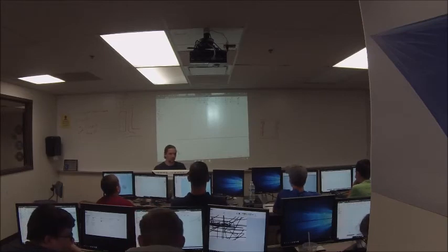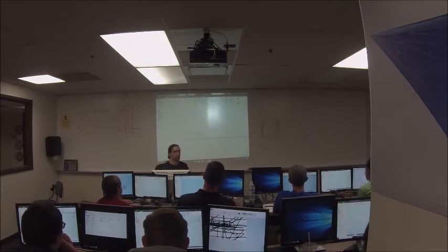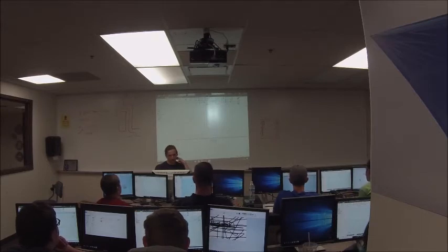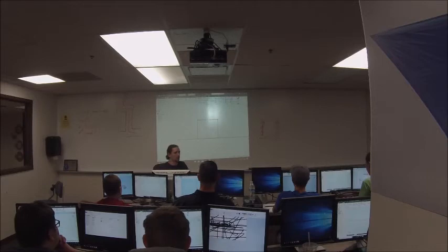Okay, now a rectangle, for instance, there's nothing special about a rectangle. A rectangle is just four lines that automatically have coincident constraints attached to them, right? That's all a rectangle is. So I can make a rectangle here, and then let's say I want to do something weird on this corner, and I don't want these two lines to be attached to each other anymore. I can press F8. Now you'll notice there are no symbols that show coincident constraints here. There's nothing there. Well, where do I go?